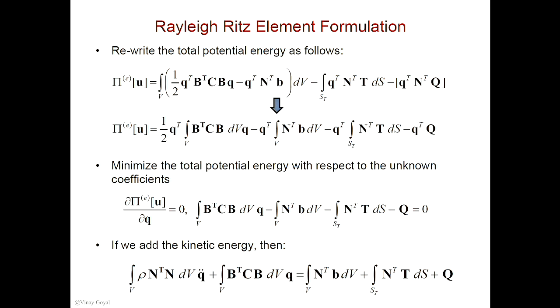Minus Q bold transpose, I put it again outside the integral. N transpose B dV minus Q transpose outside the integral again. And then this N transpose is either 1 or 0. Basically you get this. Okay. Q are the nodal unknown coefficients, the nodal unknowns that we don't know. U1, V1, W1 at node 1. U2, V2, W2 at node 2, and so forth.